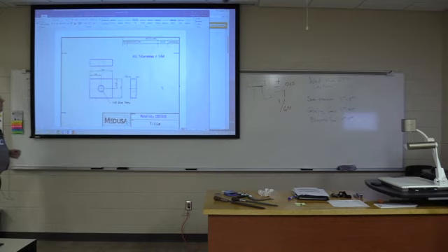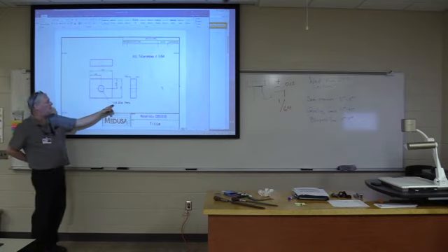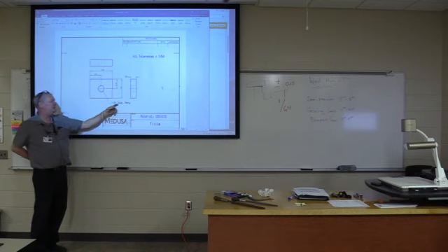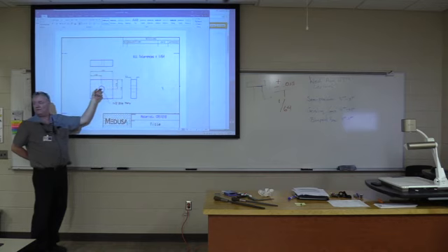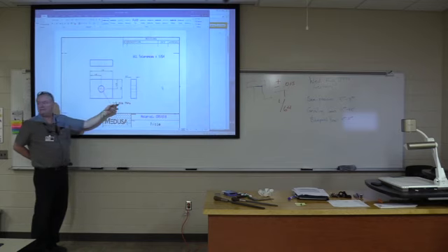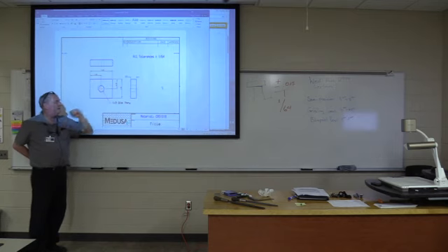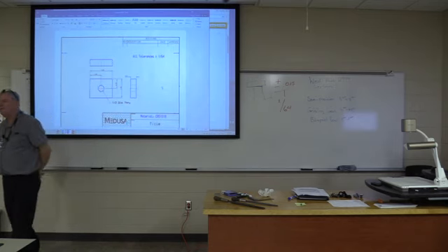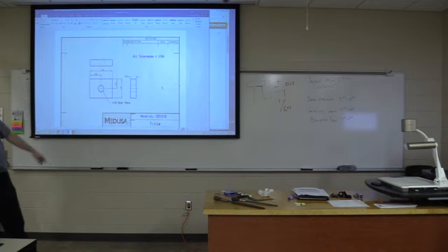So what we do generally, if the hole is larger than about 7/16 of an inch, or getting up to a 1/2 inch, you give it a smaller hole first, we'll call a pilot hole or a step drill, and then you come back with a full 1/2 inch diameter. So you let the smaller drill work its way, and then you come back with a 1/2 inch diameter drill.